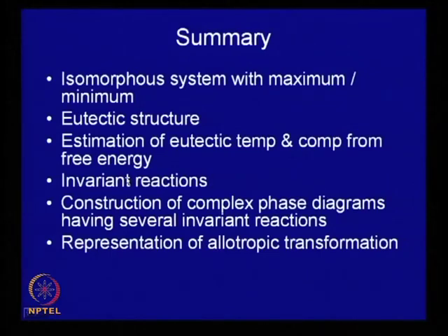I think next class we will possibly look at the deviations from ideality, the thermodynamics, and we also will look at what happens, because so far we were discussing the evolution of structure when the alloy is cooled at a very slow rate, where at every stage equilibrium is maintained. So, in liquid, the composition can easily adjust to change, because the movement of atoms is much faster than that in solid.